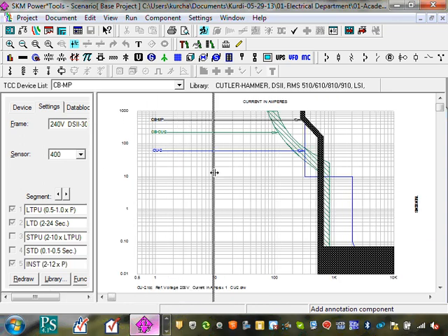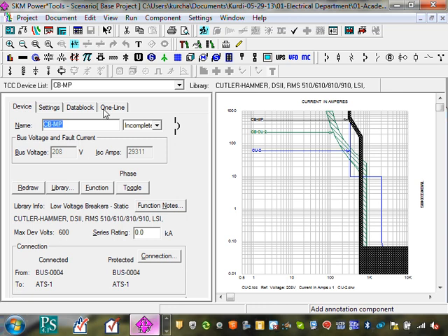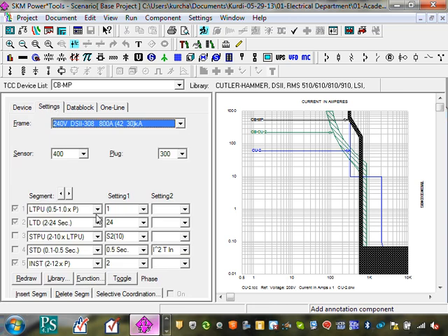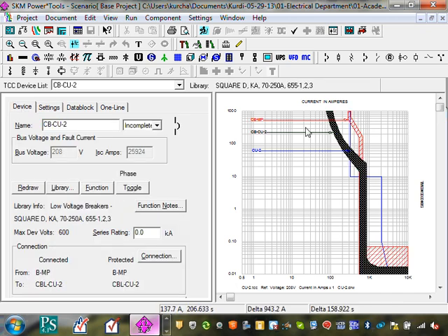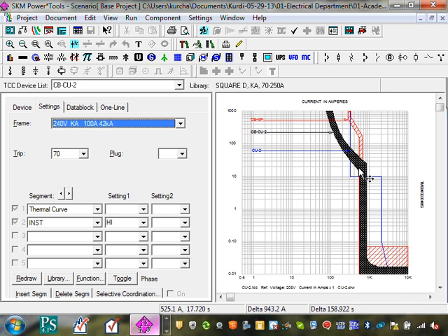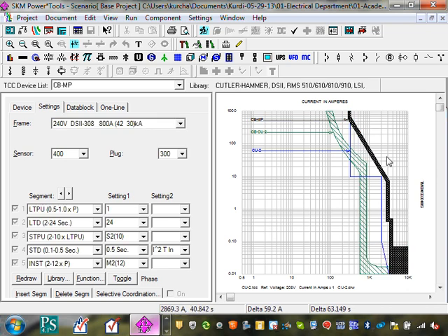So when you have a circuit breaker like this, let's go to the worst case. You can adjust all the amps. You can adjust the time here that you trip. Fixed circuit breaker, like I said, here's the fixed circuit breaker. The only setting that you can do is here. So these are the fixed and adjustable circuit breakers. Inverse time: I want you guys to look at this one.